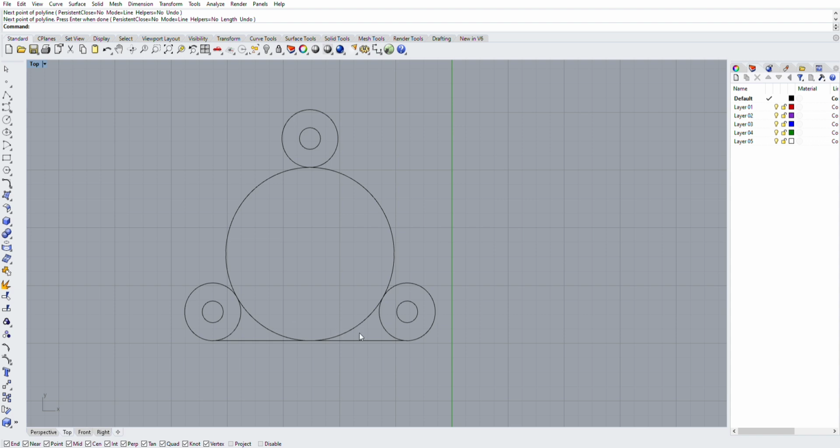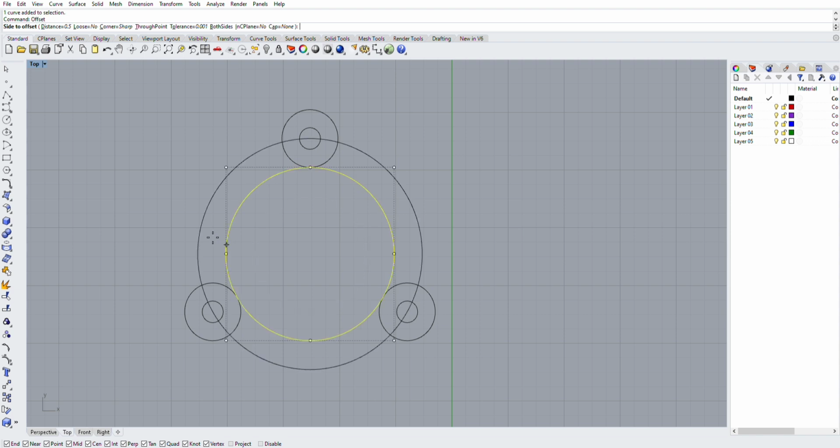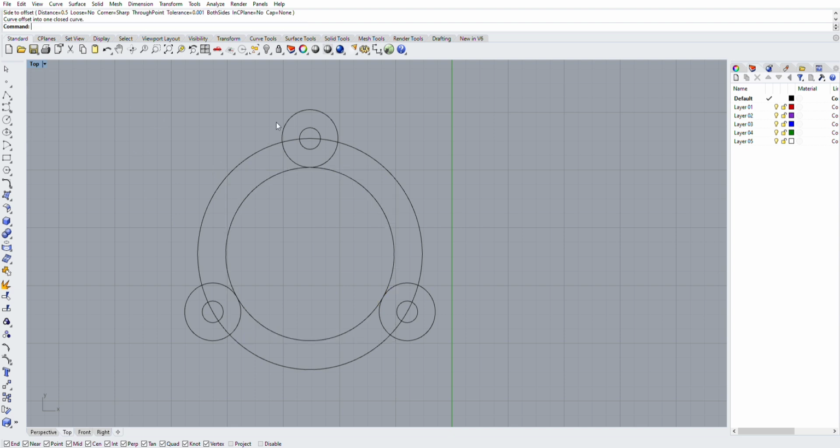Now, if we draw a straight line from our outside circle to our outside circle, we can see that it's not really giving us a flange. It's going to hit our tube. So we need something bigger than that. So we're going to offset that center by 1/2 inch. I wouldn't want to go any less than that. This is just for demonstration purposes, how quick and easy it is to make a flange like this. So we've got 1/2 inch of material all the way around.